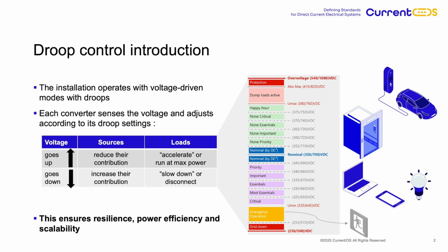This highlights a key difference between AC and DC. In AC systems, most actuators function as contactors, toggling between on and off. Think about the day-night switch for a water heater. It's either on or off. In DC, thanks to power converters embedded throughout the system, every source and load effectively has its own variable speed controller. This allows for gradual, precise adjustments.